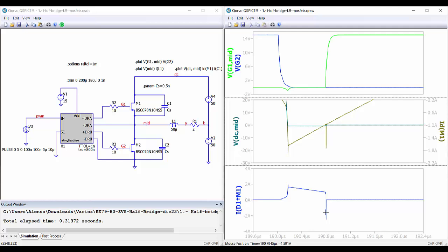understand better the switching process, but this is not possible to do directly. Even if we do the difference between the current through the diode and the current going into the drain, we won't get the current through the channel because we have the parasitic capacitance of the transistor in parallel. So maybe this could be an interesting feature for Qspice in the future.